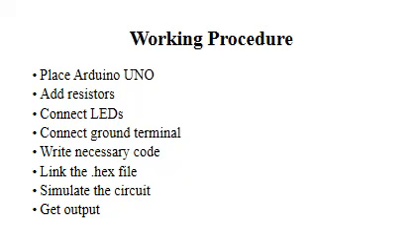If we worked with the Arduino UNO hardware in lab, we would need to connect the power supply, as it can be powered by the USB cable or by an external 9-volt battery, though it accepts voltages between 7 and 20 volts. Then we take resistors, LEDs and ground terminal, and then connect all of those using wires.